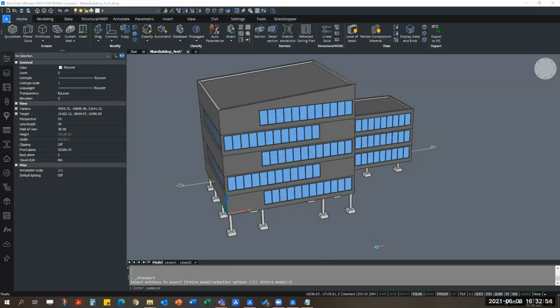Importing the map. Now that you understand how it works in the txt file, you should be able to understand that the exact same rules apply for import mapping. This time around, we're just switching from BIMDB wall, for example, to IFC wall, and writing it the other way around, so IFC wall to BIMDB wall.